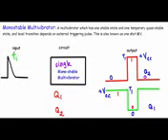When we apply this external triggering pulse, the output will go from 0 to plus VCC, or from 0 to logic 1, and it will remain at this level plus VCC as long as the pulse T1 is applied. After that, it will automatically come from 1 to logic 0, and it will stay at this level unless we apply another triggering pulse.